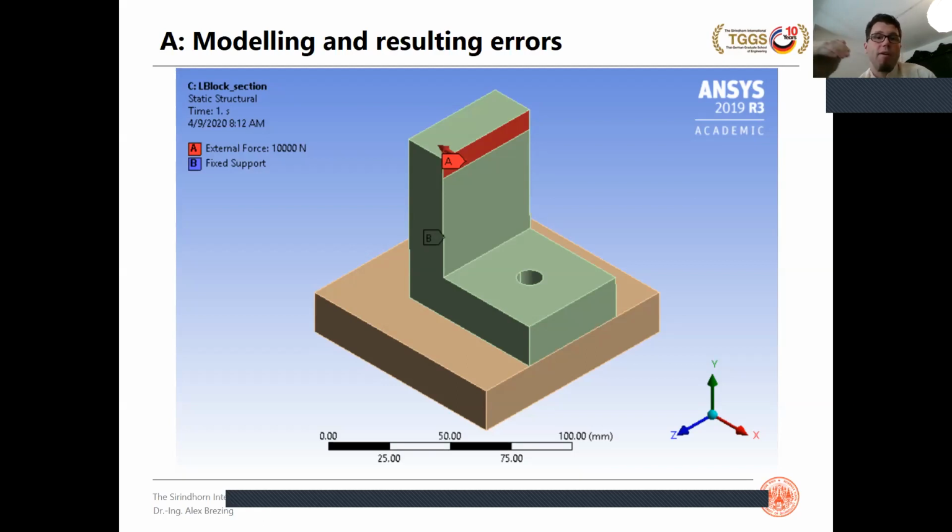In real life, we just pin down the one body at one position, and if it starts bending, it will probably lift off from the lower body and only support itself against the brown body on the edge, on the outer corner of this L. But if they're united as they are now, all the two combined horizontal parts will be much stiffer, and probably the resulting stress in the inner corner of that L-shaped aluminium part will be even higher as a result of that.